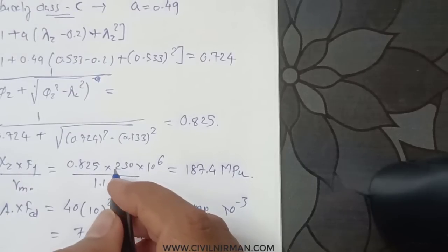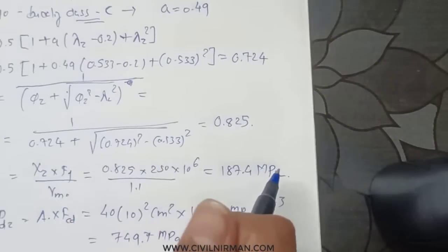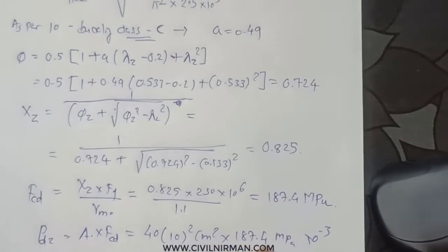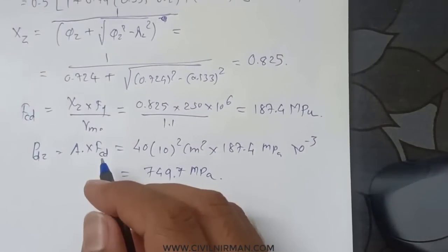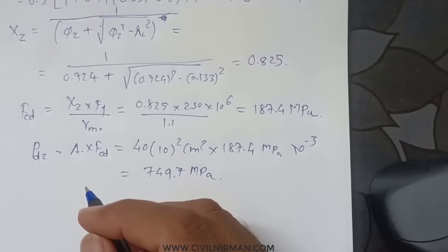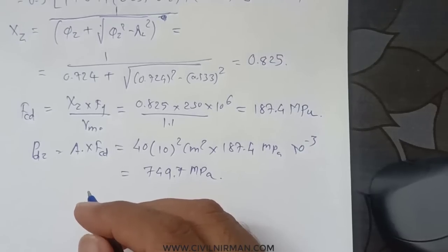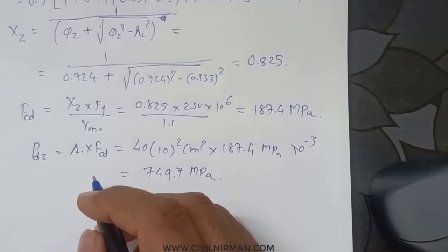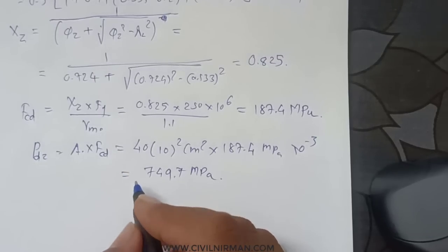Okay, so that is the p value that I got. Let me just adjust this first. Now what we will do, we will check for the axial compression about the minor principal axis. The slenderness ratio again we will work out, right, for that particular axis. So the same step we need to repeat again.